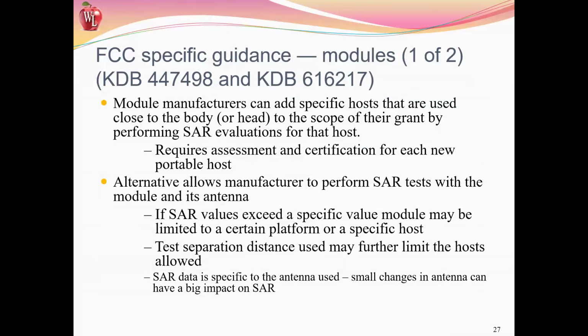There's specific guidance for modules, 447498 and 616217. Module manufacturers can add specific hosts that are used close to the body to the scope of their grants by performing SAR evaluations for that host. You've got to have the assessment and certification for each host, because depending upon the host geometry will determine how the SAR is tested, and if you move that module to another device, it may not still follow with that and will not comply.